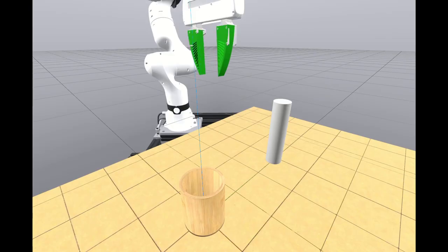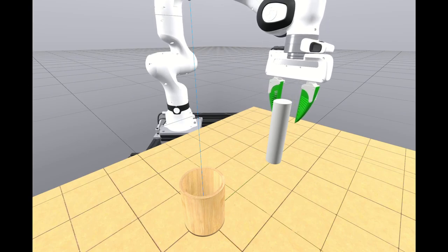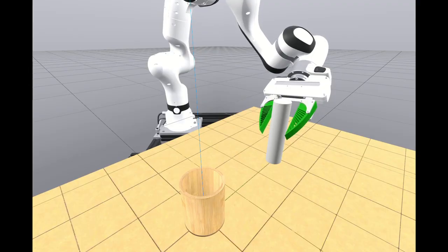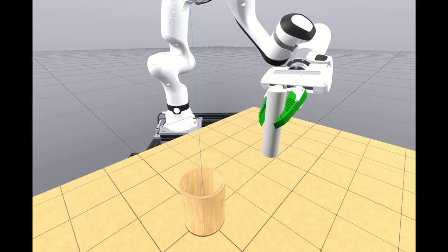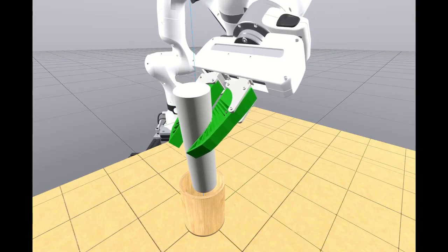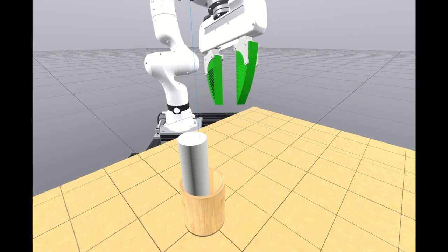Our method naturally extends to supporting frictional contact with deformable bodies. Here, we simulate deformable fin-ray gripper fingers on a Panda arm in a peg-and-hole task. The robot, teleoperated with a 6 degree of freedom space mouse, completes the task using differential inverse kinematics and a 10 millisecond time step, successfully inserting a rigid peg into a fixed holder.